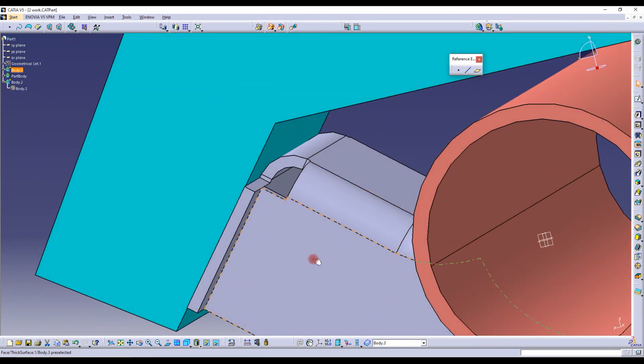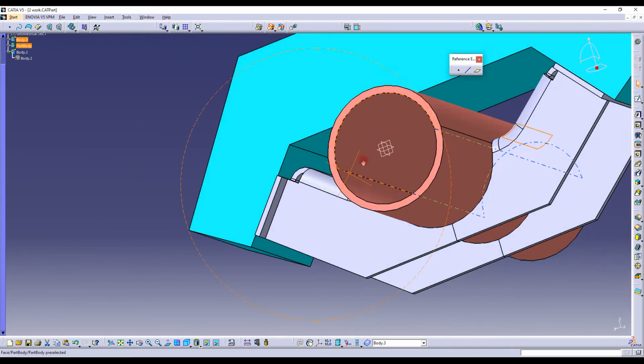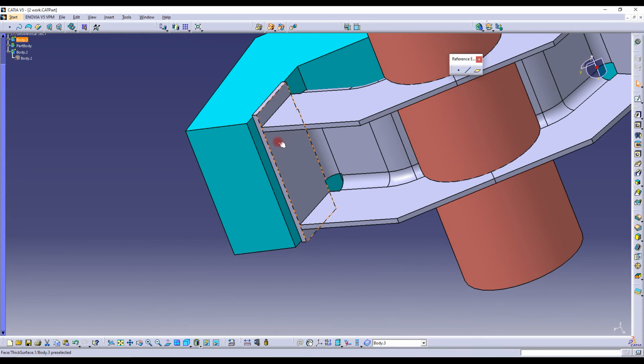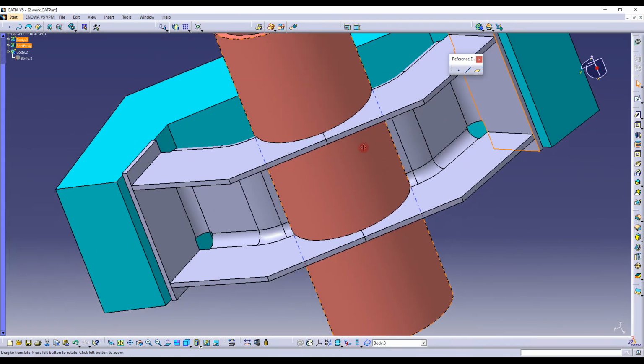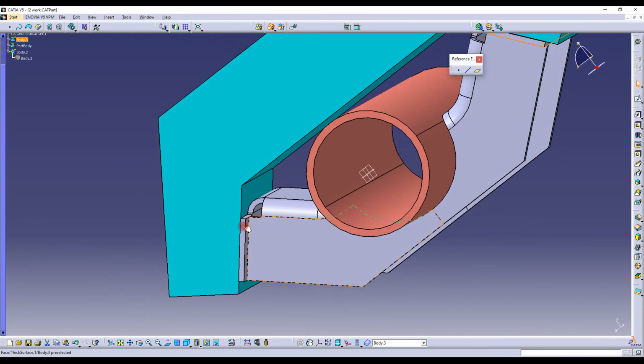Since the design is fully parametric, we can change the fillet radii, or we can increase those values which we had entered for the cutouts, 7 mm, 8 mm, 9 mm. We can go on increasing that to increase that clearance and have a better bendability of this bracket. Next, we need to create the holes, the mounting holes over here by using the pocket command, and we need to just give the fillets to all the sharp edges.